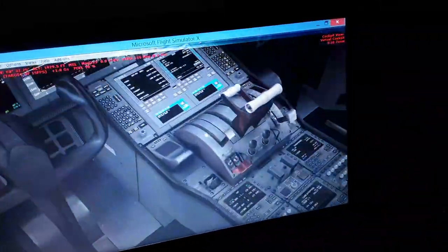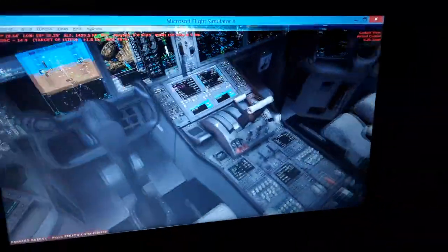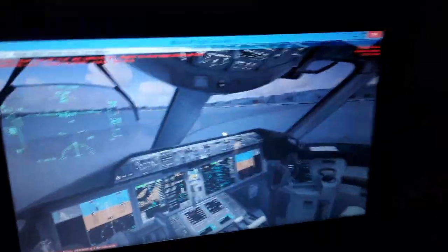So we have the flight management computer. I will use it to input all the data of the aircraft for this flight. As I told you, the takeoff gross weight, the flaps for takeoff, the aerodynamic chord position, the horizontal trim stabilizer 4.25 degrees, aerodynamic chord 23%, and the takeoff speeds are going to be calculated: the V1, VR, and V2 for this runway length.